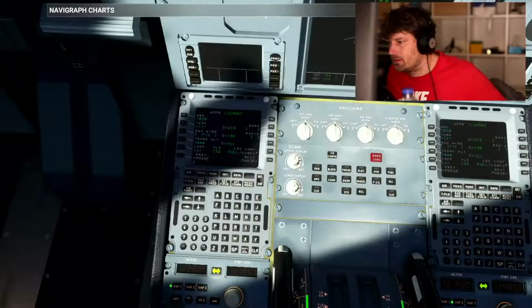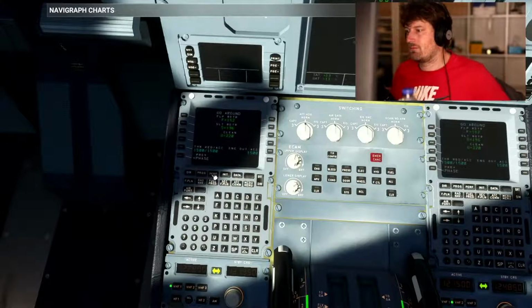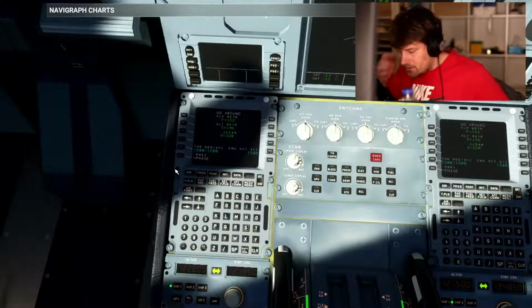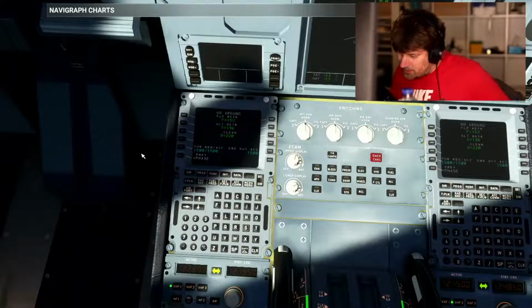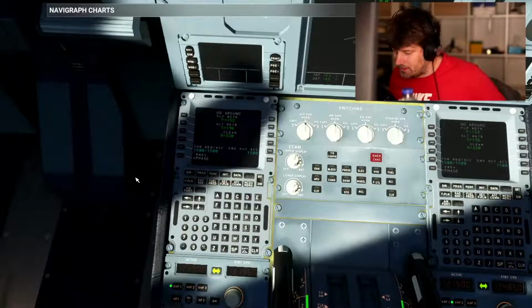Oops. Is our baro minimum height. Good, good, good. Everything coming together. Go-around has normal values here. So, looking at our checklist, the MCDU data has been set up, the RAD NAV page configured, the IRS is aligned, our flight plan has been reviewed, takeoff briefing has been done, and that's the cockpit preparation done. So let's have a look at the pre-startup.